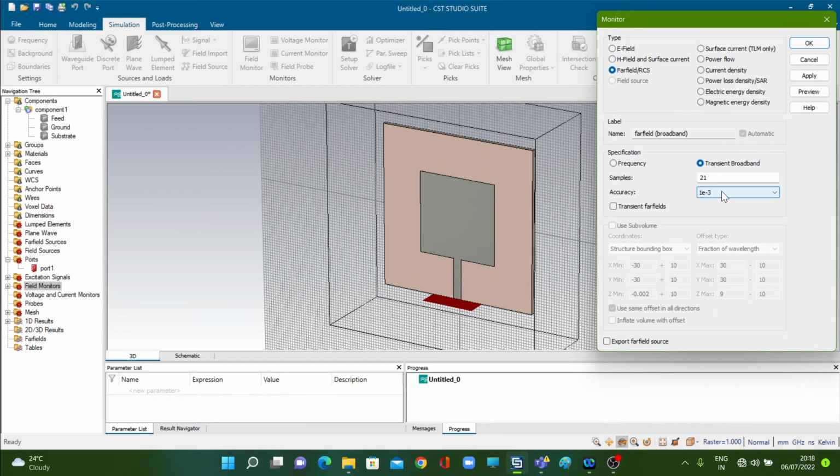On the other hand, if you reduce the number of samples, you will get a step-like curve. You will not get a gradual, smooth curve. You will get a step-like plot, so that is not that accurate. But at the same time, the computation will be very fast. So we will optimize. We will increase this a bit. Let us keep it to 30.